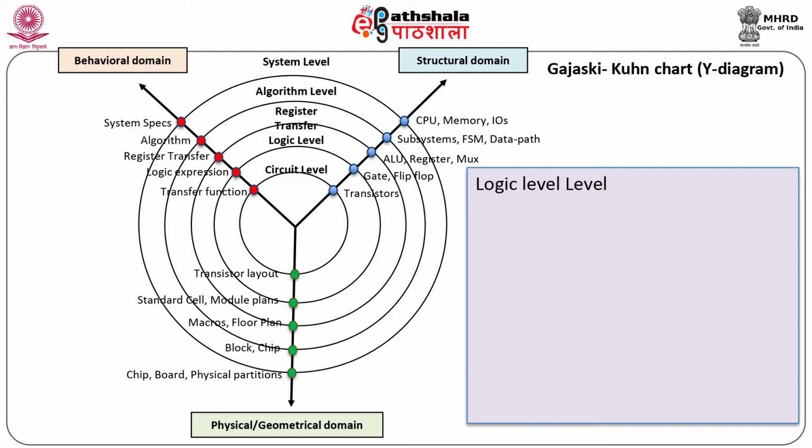Register transfer level. In this level of abstraction, the basic building blocks are some simple registers and data routing elements like multiplexers. Register transfer describes a design methodology in which the data is transferred between storage registers and other logic units. Communication signals are frequently grouped together and interpreted as either unsigned integer or some binary state.